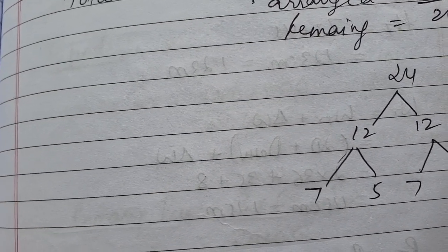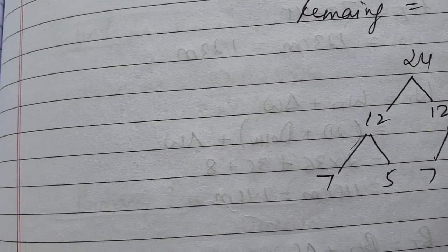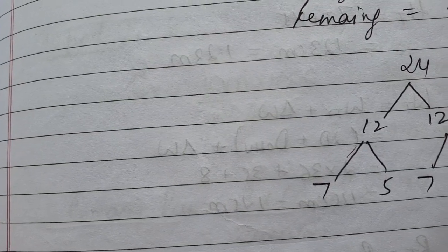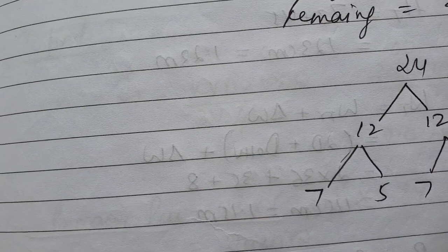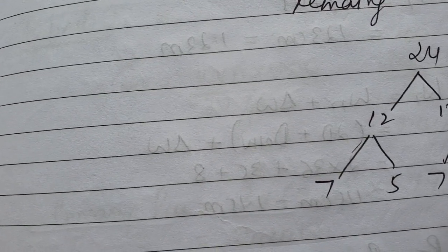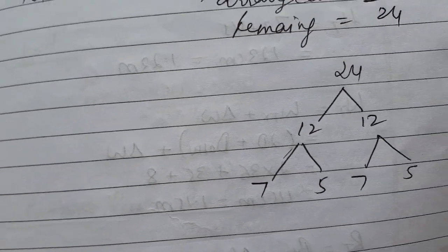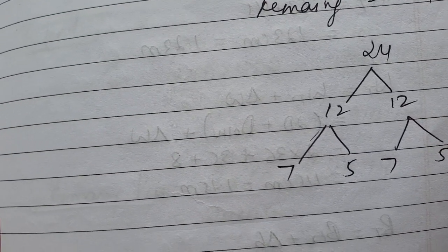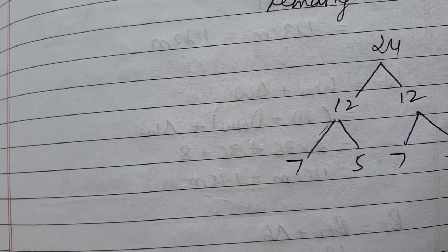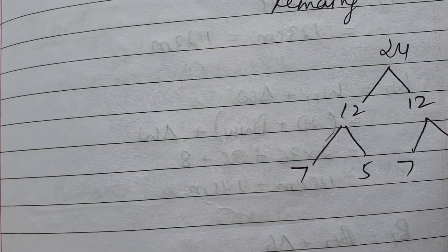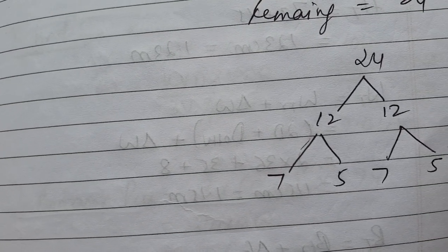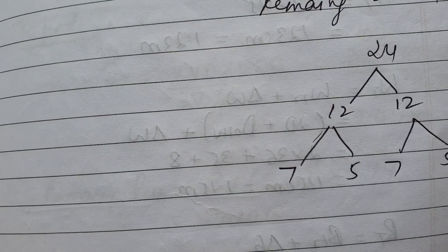As I have already told you, the number of cooling tubes along the width are 14. So when you divide 14 by 2, 7 will be the number. And along the breadth the maximum number we can place is 5. So I am taking 7 and 5. It means 7 cooling tubes along the width in second row arrangement and 5 along the breadth in second row arrangement.